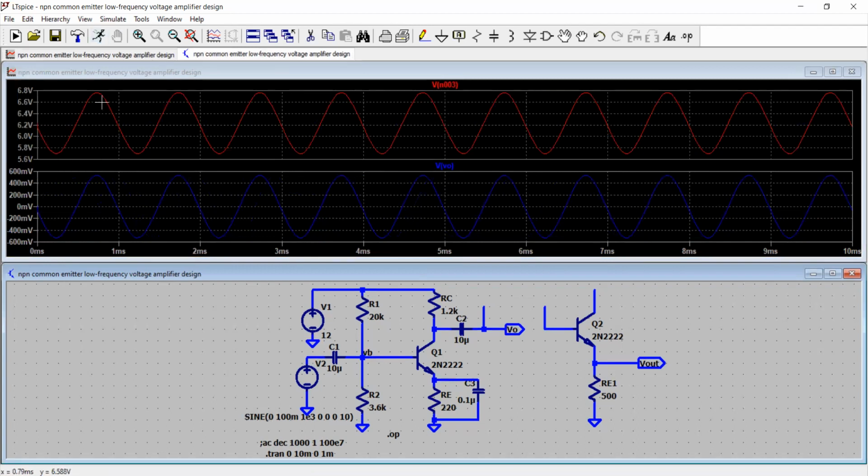The DC bias level for the input is 6.2, and then you have a swing, but the DC bias level of the output is now 0. And from the 0, you have about 600 millivolt signals. So this is the importance of adding the capacitance there. Okay. If you AC coupled this output to the input of this stage, you can also investigate the effect of it.